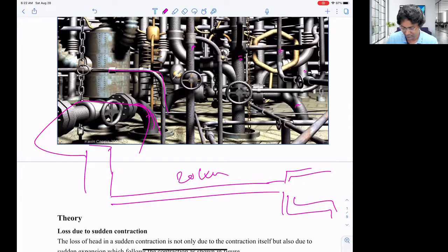So if we know that this is our head loss, like 50 meters, we lose 50 meters of head. What does 50 meters mean? It means if we have water and the energy is 50 meters, it is related to a 50 meter height of water, so that much energy we will lose. The water of a 50 meter column can do the same task, the energy or the force, so we'll lose that much energy. That's why we'll have very little pressure.